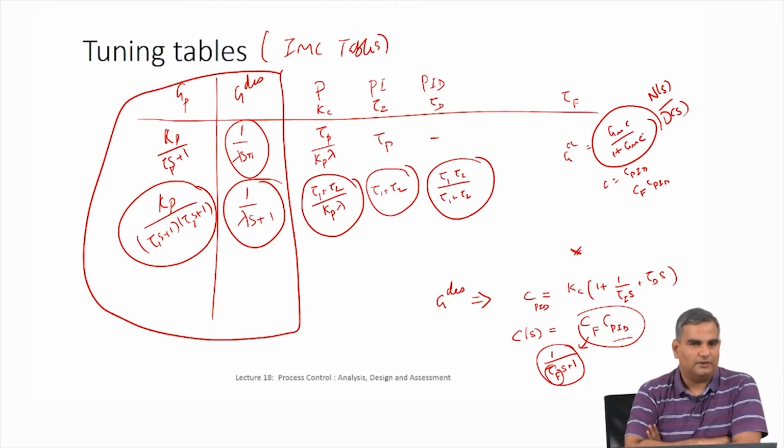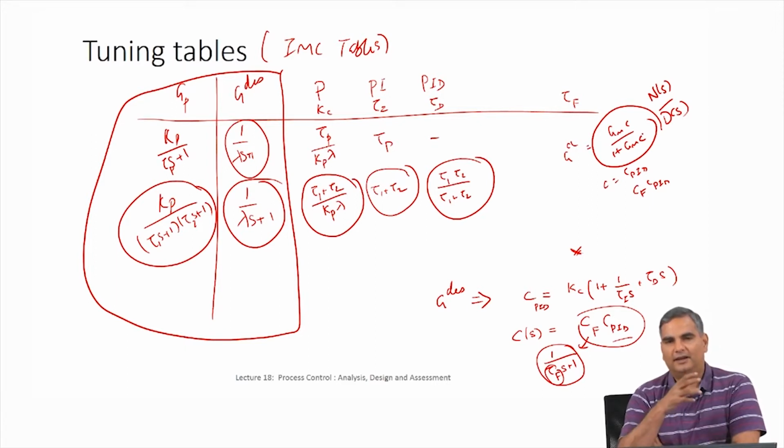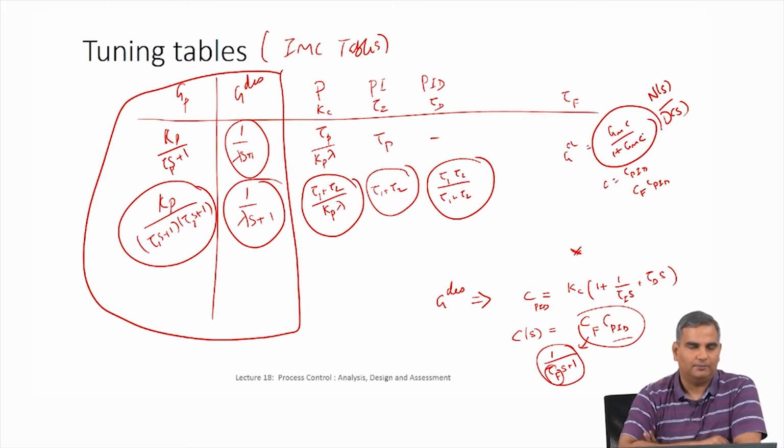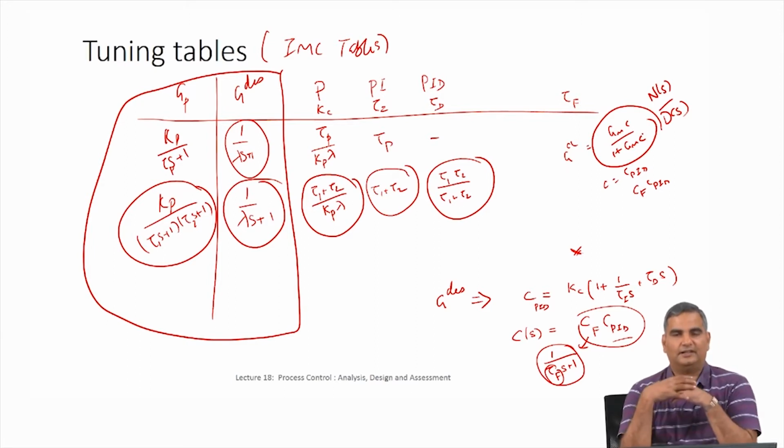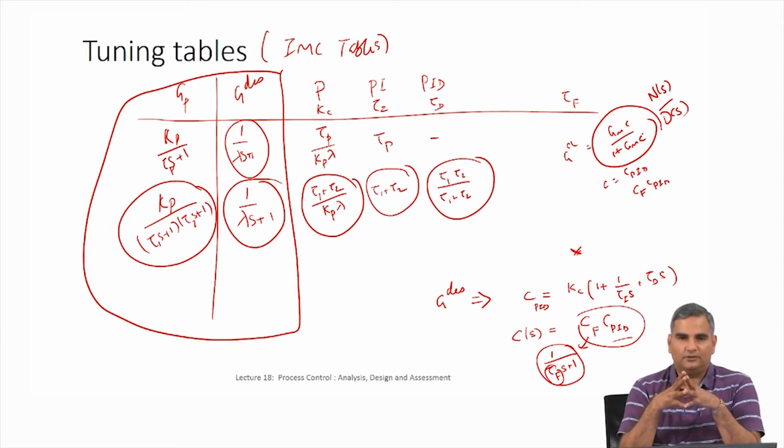All of that to some extent depends on the design that you have. So if you have a particular line where you put in a valve, flow in could become a manipulated variable. But if you had a valve but you did not manipulate it at all, left it at only one position, then it can actually be a disturbance variable. So it is important to understand conceptually what these mean, so that when you look at the design you are able to see where I can manipulate the variables, where I have to treat variables as disturbance variables and so on.